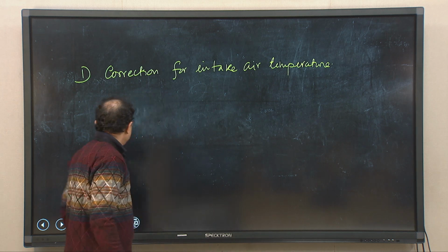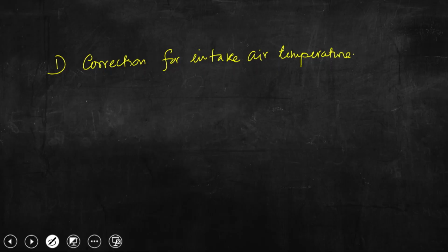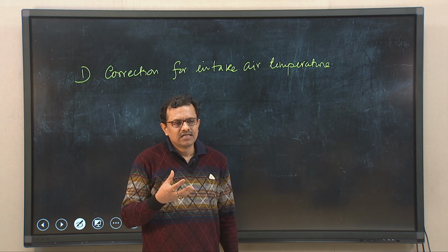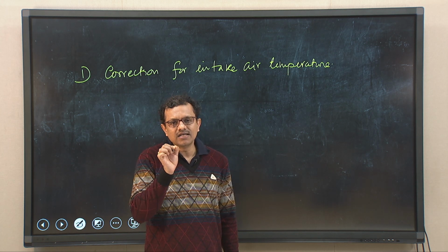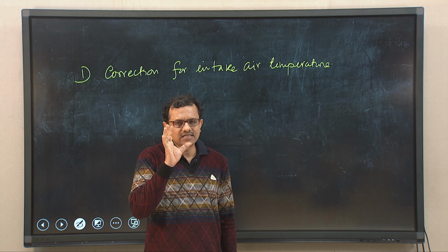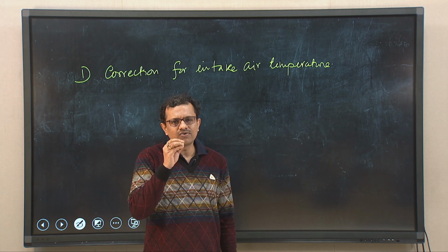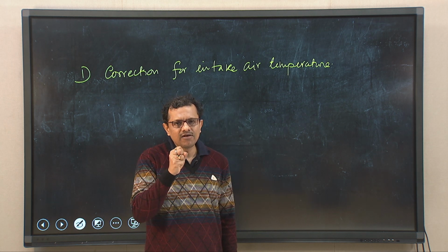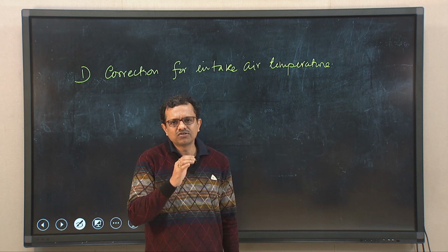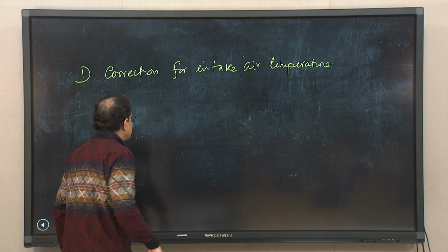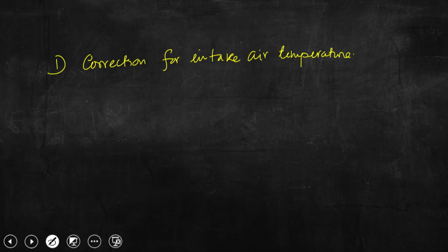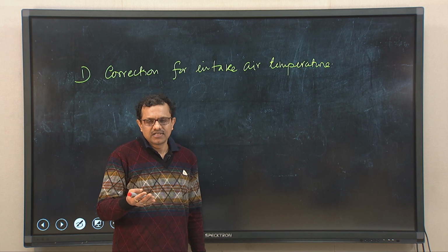So, we all know that if the air is cold, it will be more dense, right. So, depending on the ambient temperature, some corrections are needed for the injectors to supply the required quantity of fuel so as to maintain close to the stoichiometric air fuel ratio for efficient combustion. The colder the air, the denser it becomes, that you all know.